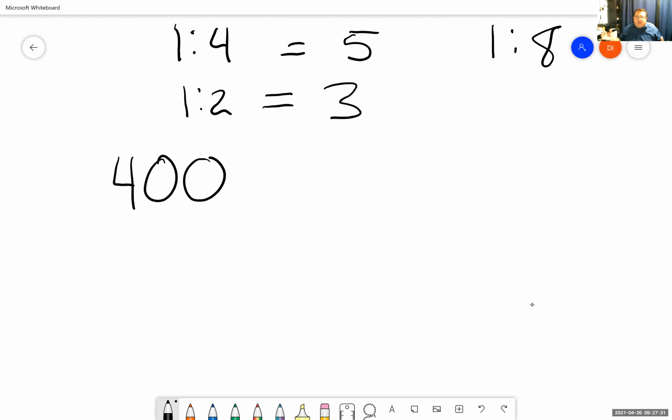Some will tell you as low as 1,500 square feet per gallon. Others will go as high as 3,000. So the industry standard, again, according to our book, for floor finish, the coverage rate is 2,500 square feet that 1 gallon would cover. Okay, but that is 1 coat of product.